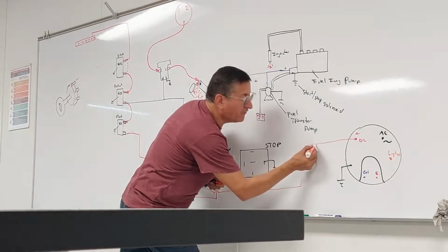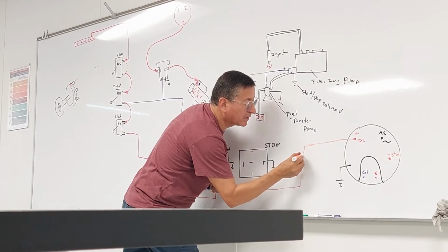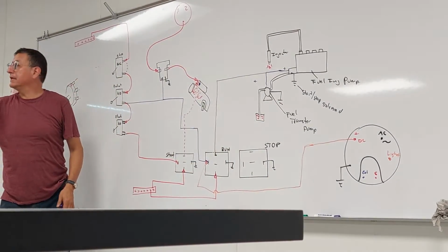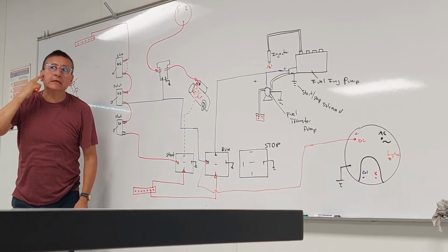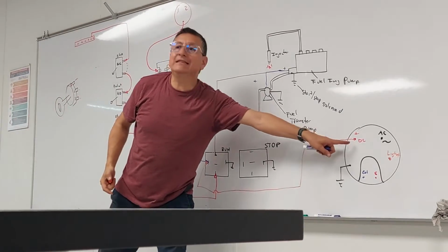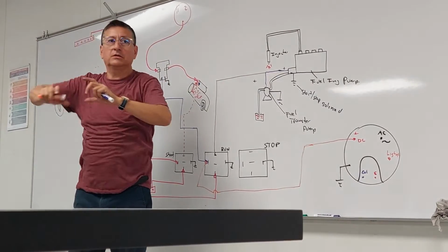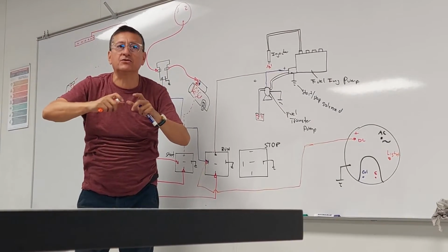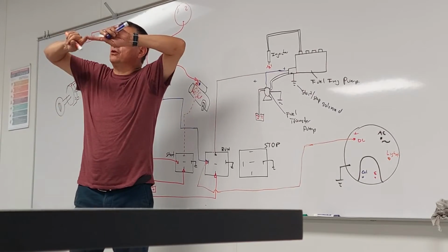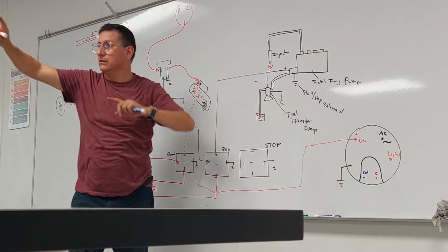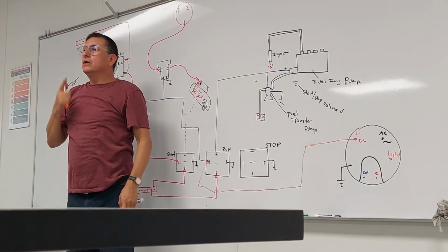I have one inconvenience. Look at this. During the preheat, you remember that the DC output is coming from the stator, not the rotor. The rotor is the excitation with the magnet. You remember? And the stator produces the AC output, which is rectified into DC, in the alternator.